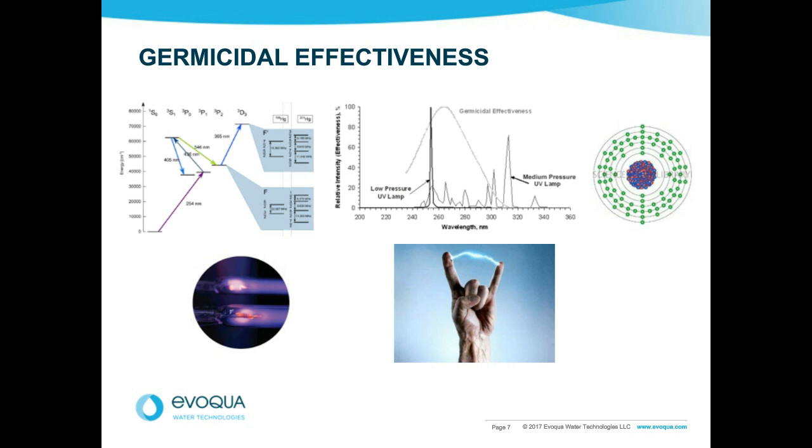Thanks. The next question, are there any applications that are considered ideal or in which UV is more commonly used versus other technologies? I think it's the standard now for RO permeate. It's becoming the standard in dairies to replace pasteurizers. It's a very common barrier now for drinking water because of the chlorine tolerance. Ships use UV to disinfect ballast water, although UV is losing favor in ballast water in favor of some of the electrochlorination techniques.